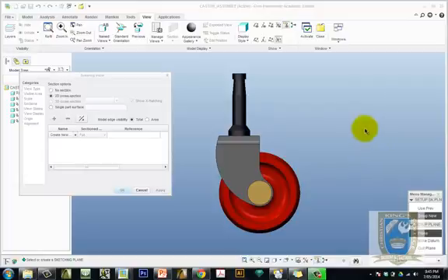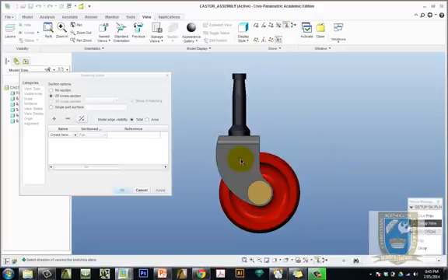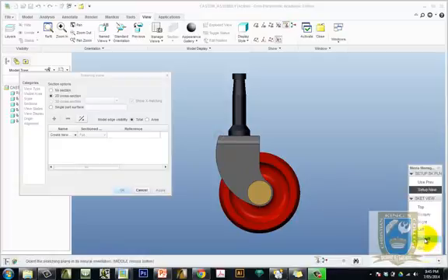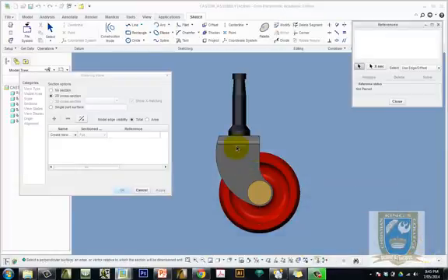At that point, it dumps us out of the drawing and takes us back to the assembly model. It wants us to actually draw the offset section lines on this model. To do that, the first thing you need is to select the plane that you're going to draw the lines on. So I'm just going to select this flat surface here. And it's asking me, is that okay? I say it's okay. And I click on default view, and that just makes me look down on top of that.